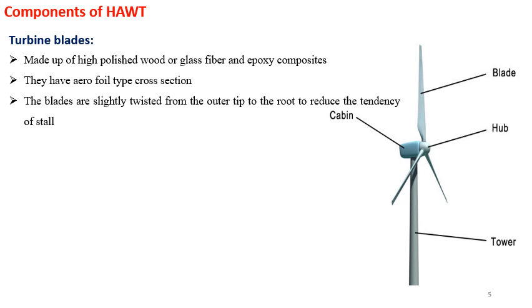Very large aerofoil rotors can turn much more slowly, typically 20 to 40 rpm, but the blade tip speeds are comparable, 65 to 110 meters per second, or up to 250 to 400 kilometers per hour.